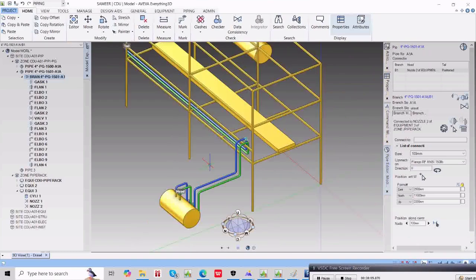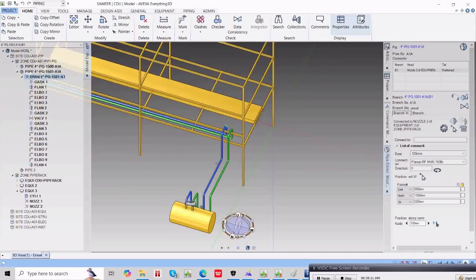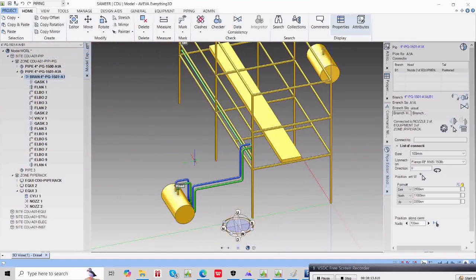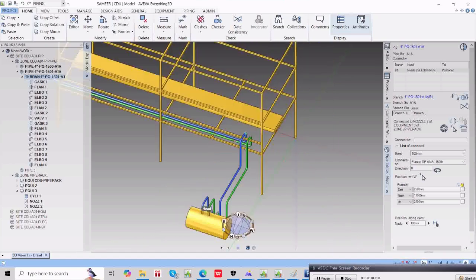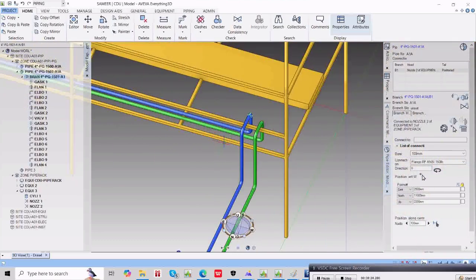Now let us assume we have one more piping, and that piping is with a flange. So one is piping and one is with a flange. Or now let's suppose we have two flanges. First of all, always remember that in the pipe rack we don't put any flanged item. Very rarely you will get an orifice flow meter, because you need to maintain a straight pipe piece. That's why sometimes we put an orifice.